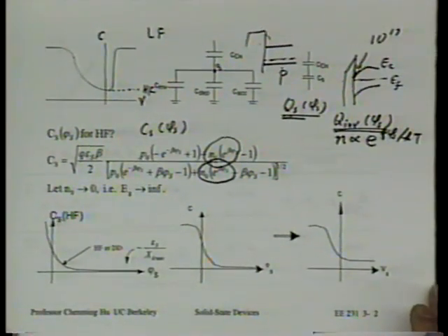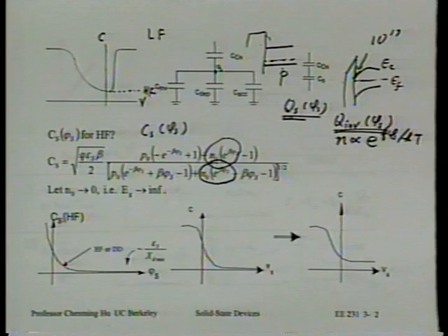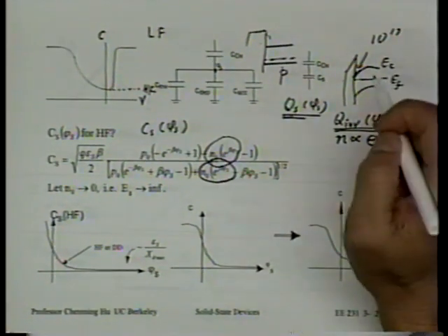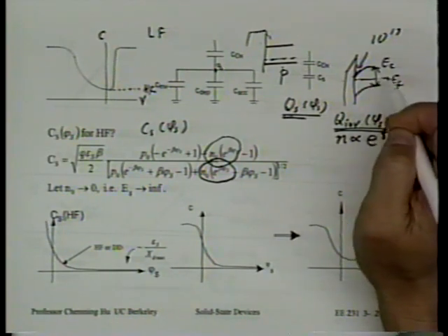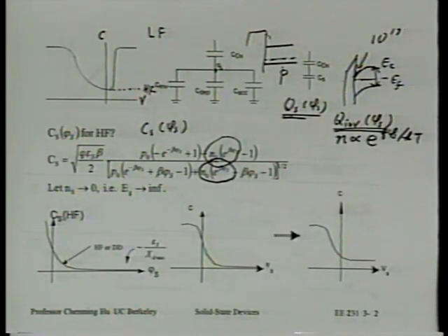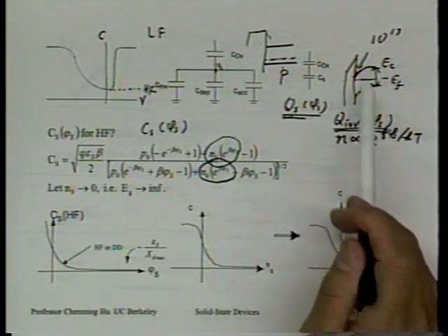So now let's go back to this low frequency. If we wait several minutes, eventually electrons will be created by thermal generation. And one thing we should know is that we should have confidence that equilibrium will always be reached if we're patient enough. Usually in a typical piece of semiconductor, it will take several minutes for the equilibrium electrons to be generated.